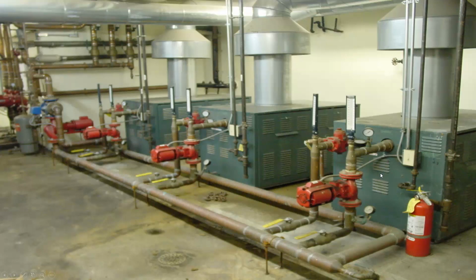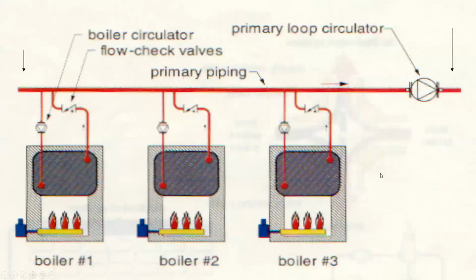One of the downsides to this is called one pipe primary, secondary. So if you remember, sometimes the temperature can degrade, from one to the next to the next. If I'm heating zones, I'm taking the heat away, I'm lowering my supply temp. If I'm in the boiler room, I'm adding heat. So I'm actually taking one temp and increasing it. That's going to the next boiler. That's going to the next boiler. So here's a really quick example. And when I say quick, I mean quick.